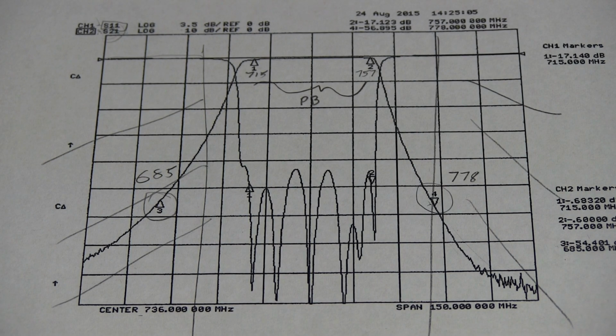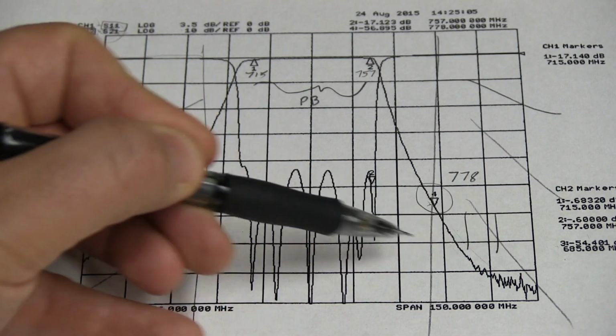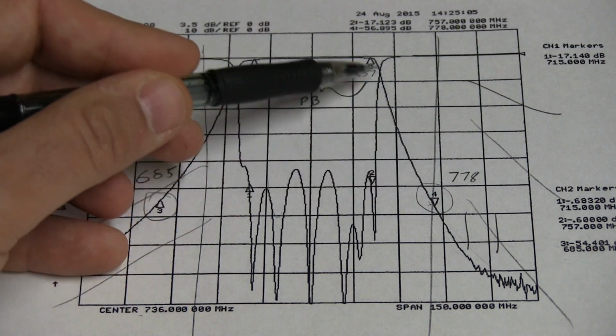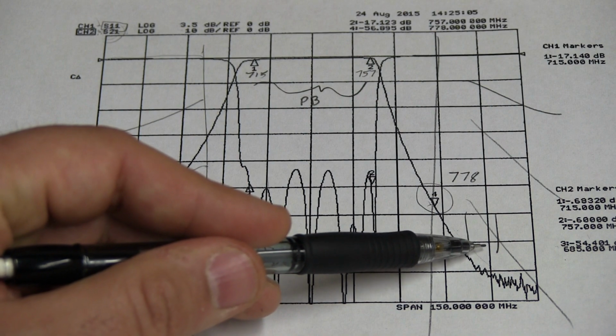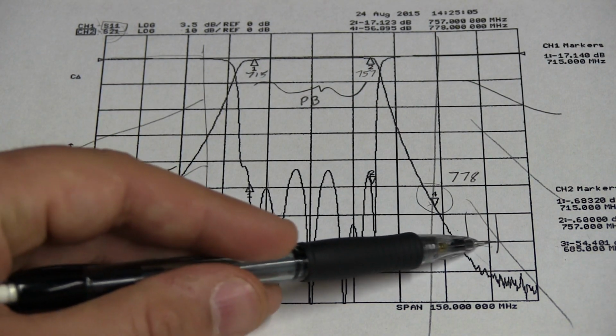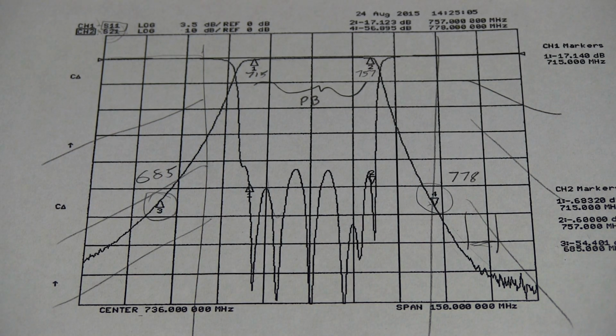And that will guide your decision in picking a filter, where you're given a system and the people doing the link budgets say, hey, we have a receiver in this area right here. So anything coming out of this transmitter needs to be really knocked down so that we don't interfere with the receiver in this band right here. So that's kind of the practical considerations when selecting a filter.